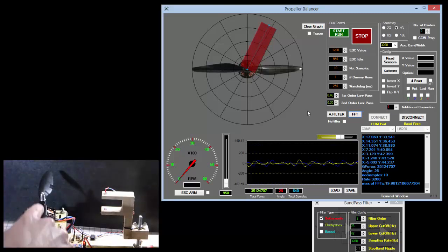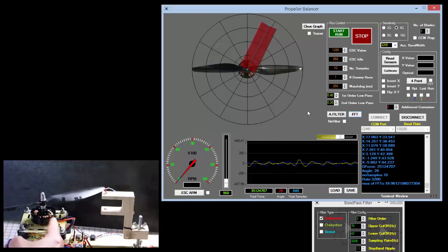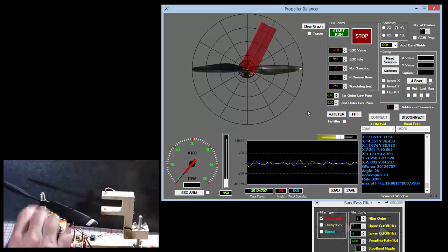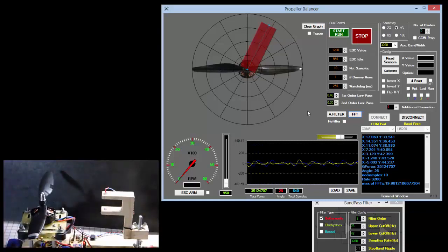Now, with that said, again, don't forget that what I did from a calibration standpoint is I placed a piece of tape on the blade, either here or there. But in order for you to do a complete calibration, you would have to remove the tape and then also place tape on the bell right here and there. Look at the previous calibration videos, because we really also need to take care of the vectors that might be pointing here and here before we can consider this completely calibrated